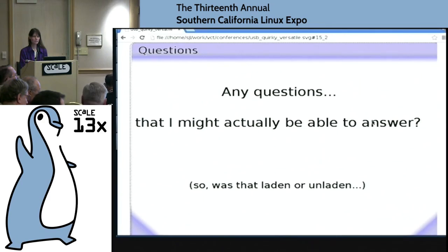So on the gadget side, I've been down that road. For FunctionFS, you can go to Danx's site, where the U-Boot tree is hosted. On their Git tree, there's a PTP gadget driver, right? So when FunctionFS came in, the kernel was being discussed. That was one of the reference protocols that was implemented. It's a pretty good implementation of a FunctionFS based gadget. I've used that for some of my projects as a guideline and so forth.